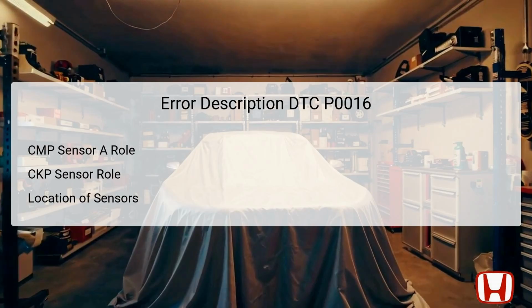The CKP sensor, on the other hand, is responsible for monitoring the crankshaft's position and speed, which directly influences ignition timing and fuel injection. This sensor is typically mounted on the engine block or timing cover. Both sensors work in tandem to ensure that the engine operates smoothly and efficiently.